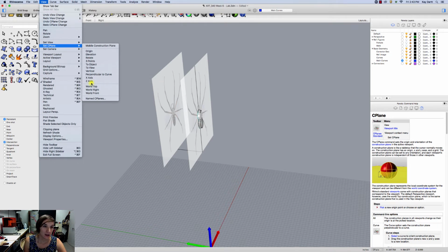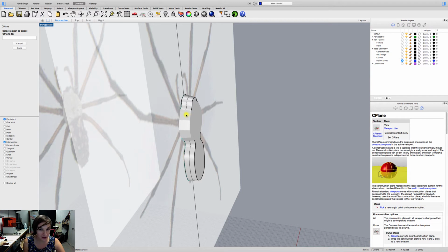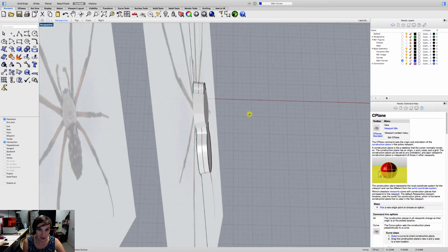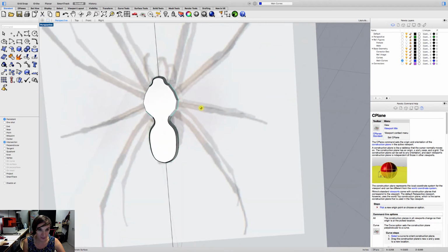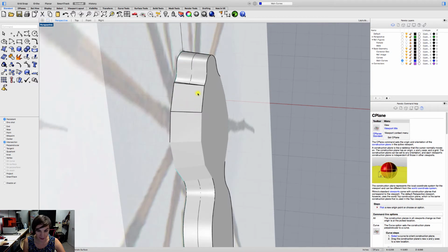All right. I am now going to show you the toObject command, which automatically snaps a coordinate plane to a specific object in generally kind of the area where you try to click the object. So I'm going to select this surface, and you can see it's automatically brought that coordinate plane right to that surface. And sometimes if it's a nice easy edge surface, it will bring it to the centroid of that surface.